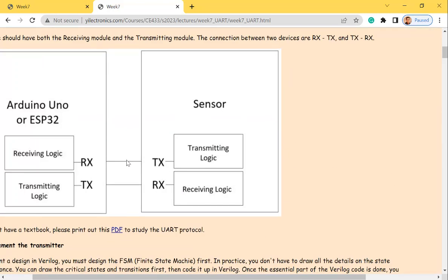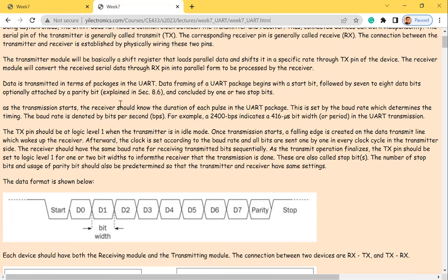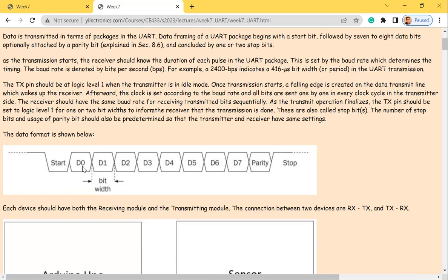1 line is 1 bit. Why do you need an 8-bit output for the serial communication? That's parallel, like 8-bit. That's the whole purpose. We need a 1-bit output. Is that 1 bit? It's just 1 line. I pull it down, and after I pull it down, then the next cycle will be whatever, 1 or 0, doesn't matter. It's the data, D0, but just 1 line.